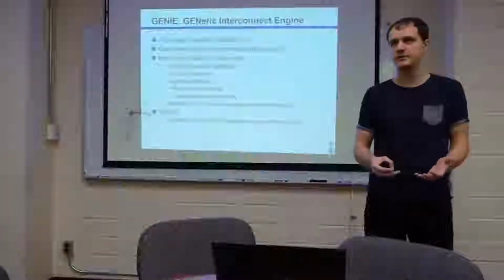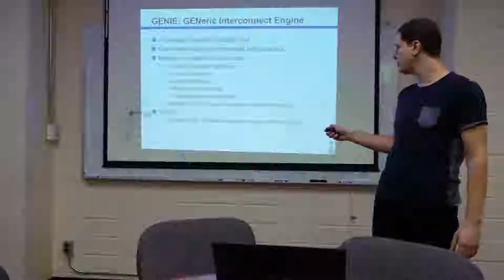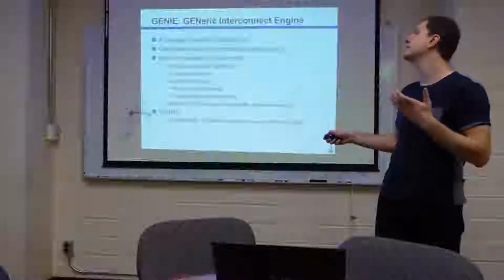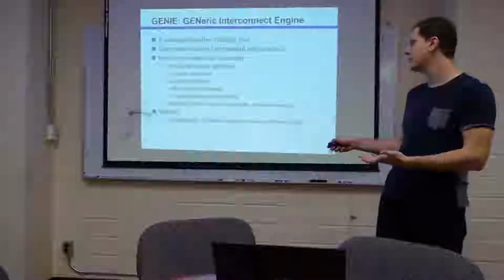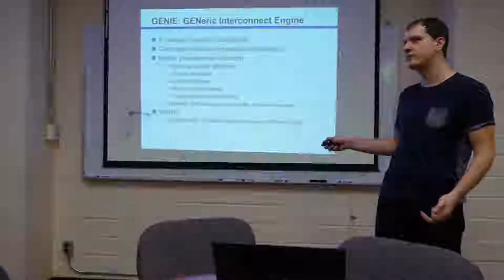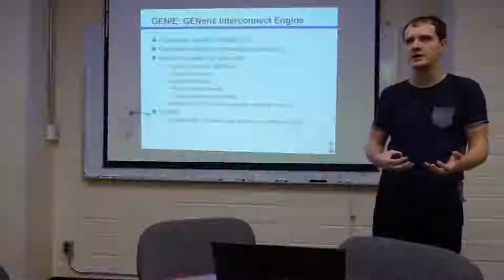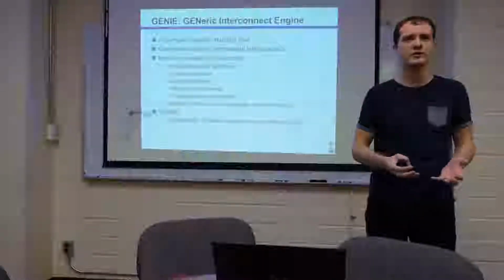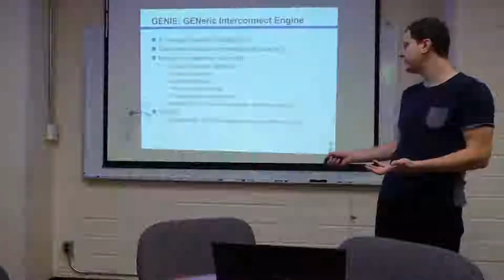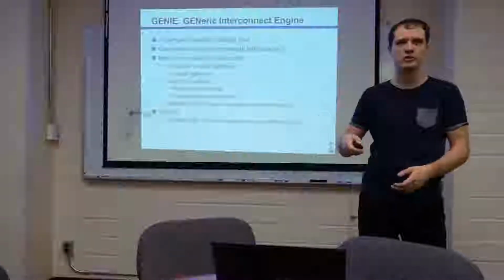And through the script, programmatically, you define all the inputs I talked about. You define your functional modules, including the interfaces. You define the system that contains instantiations of those modules and the logical connectivity between them. And you're also able to provide additional metadata, like constraints about those links, about the system, about things you desire to be done to control the tool. And as output, it generates synthesizable SystemVerilog for each system, as I showed a few slides back.